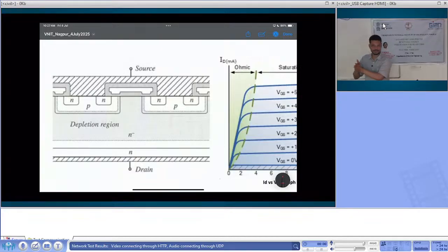The trade-off is still there. If you want to build ultra high voltages, you would still want to do IGBTs, not MOSFETs, but the trade-off has shifted. So in silicon carbide you would see popularly 1.2 kV MOSFETs, 1700 volt MOSFETs, 2.2 kV MOSFETs, even 3.3 kV MOSFETs, which in silicon you don't have. So in summary, these silicon carbide devices have allowed us to do high frequency power electronics at a medium voltage. That's the basis for why we started doing this work, which was earlier not possible. We could do it with IGBT but not with MOSFETs.